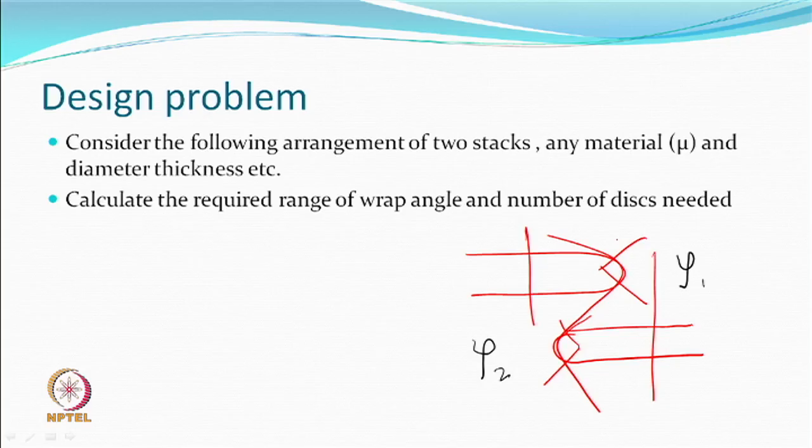The twister angle should be based on the denier range, because that will change the helix angle. So, between this helix angle and that helix angle, this range of denier should be processed here. If you have a different range of denier, then you use this, etc. But the wrap angle, how do we decide? Where do you put the guides for that matter, right? That will again be based on the range of helix angles. So, you can look at this design problem, you will solve this design problem.